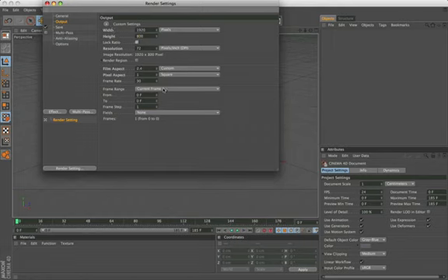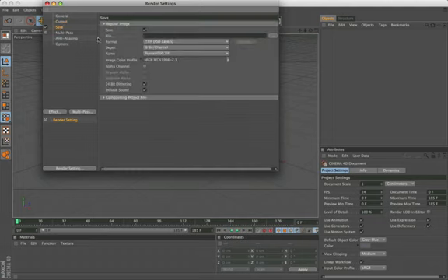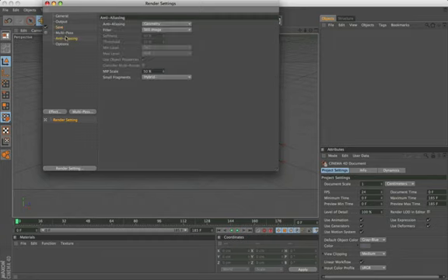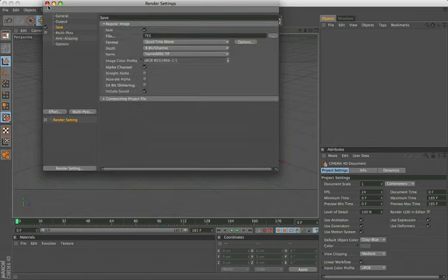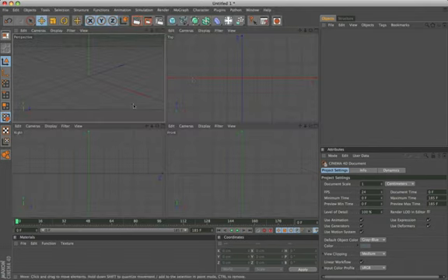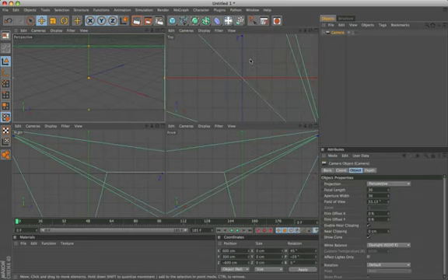We set all frames. Save as QuickTime Movie, and activate Alpha Channel. Anti-aliasing on best. Finally, insert a camera, and we set the Z coordinate to -1920.